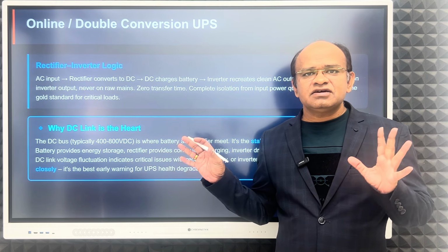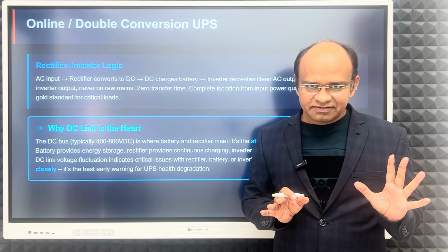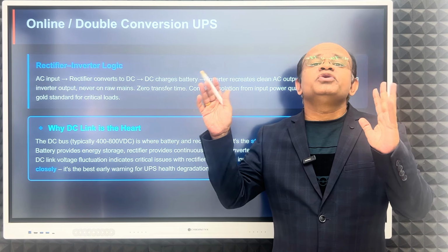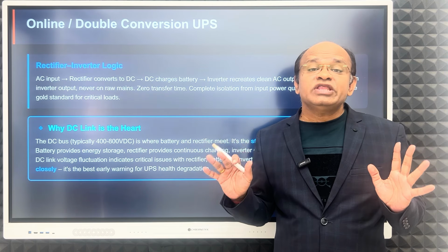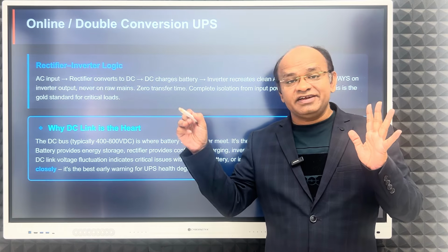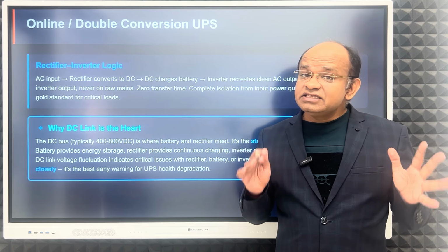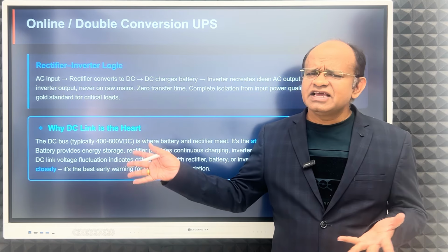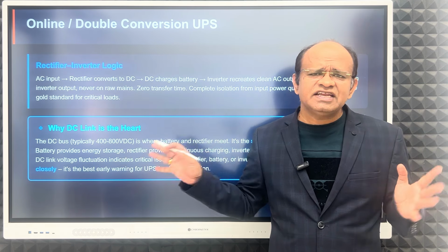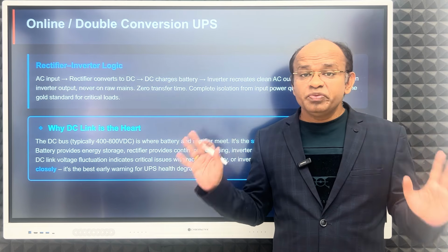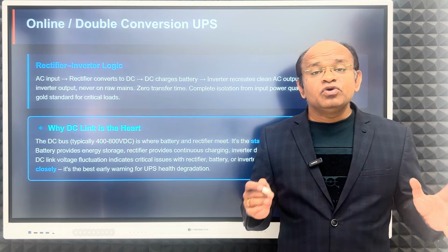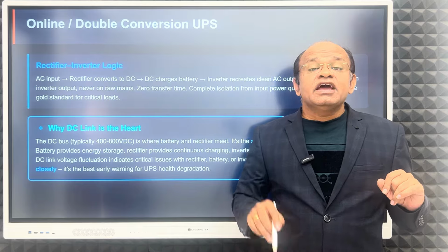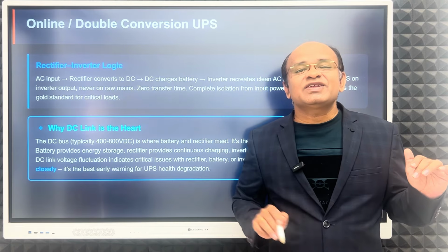Now it is an era of IoT devices. So you should have the DC bus voltage monitored continuously on your BMS system, so that you have the behavior pattern of it. You should save it. Easily you can connect this UPS to your communication channel by SNMP protocol or BACnet protocol, which we have seen. SNMP protocol is generally used in UPS, which can be connected to your IoT or BMS devices, and then you can have the graph of it and put thresholds for that.